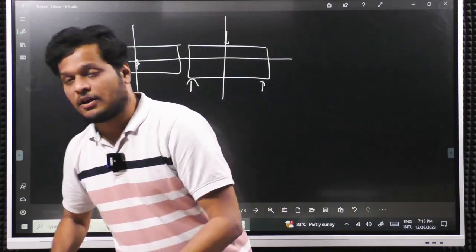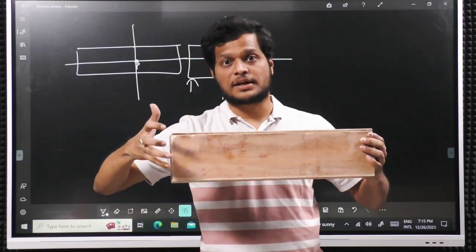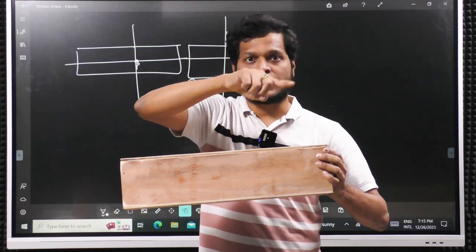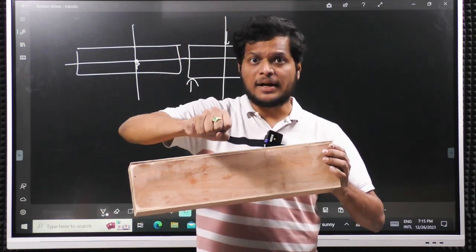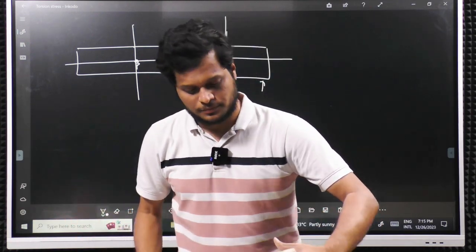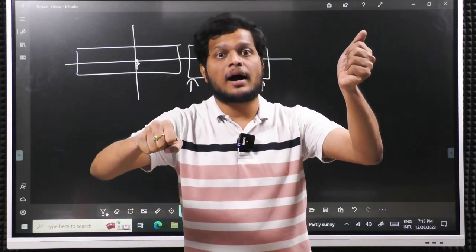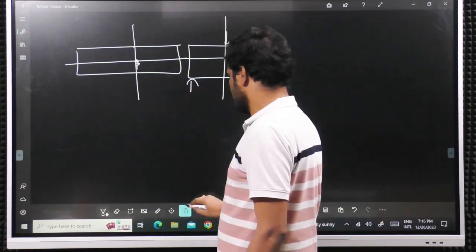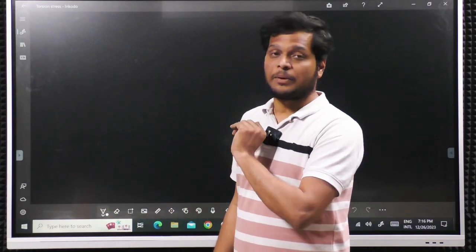Okay. If it is with respect to z, it will get twisted. With respect to z, it has to twist. So if you place a load here, it will bend. If you place the load slightly away, it will bend and twist. What will happen? It will bend and twist because of the torsion you are applying. Okay. So I hope you understood this for the beam.